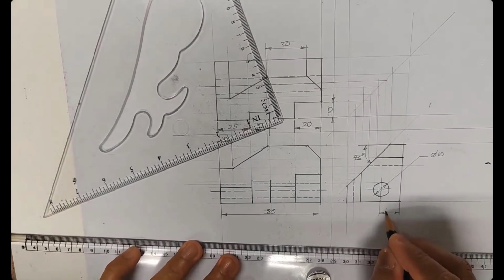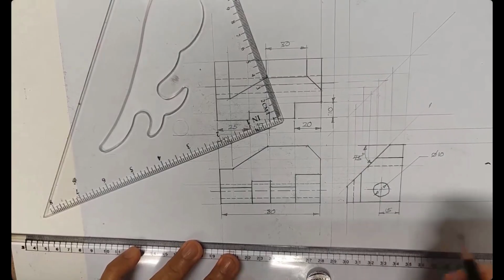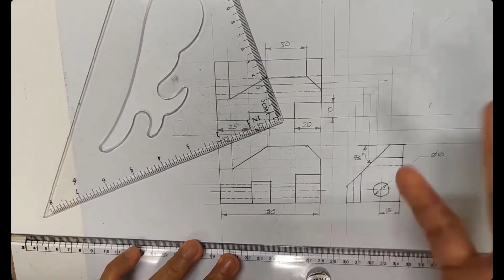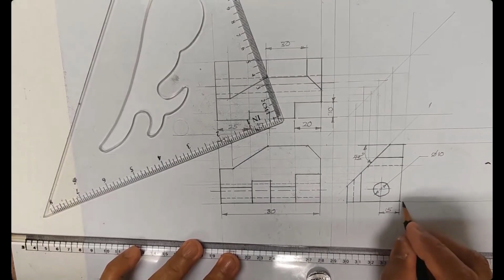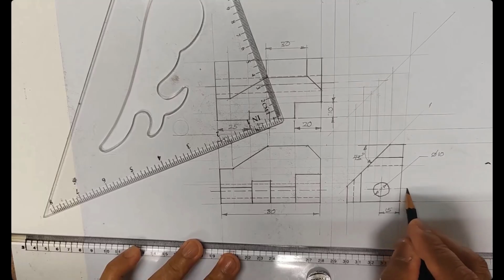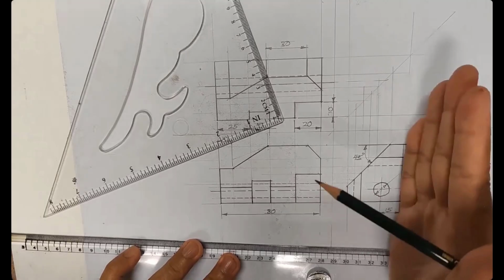15 from there. So you write it properly, 15, right? And also goes here. Okay, I just need to be quick. I'm doing it by hand, but use a square or ruler, with a gap on the extension line here. This is your center mark of the circle, gap here. Your extension line passes through the object here, not too close, about 2 letter height.